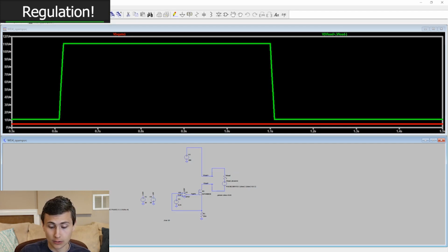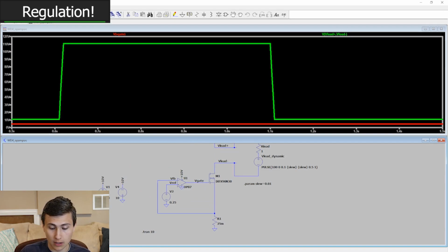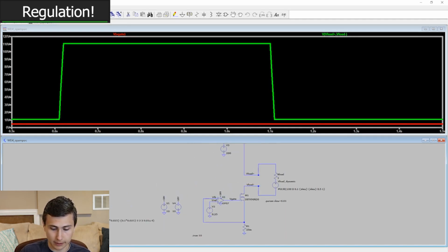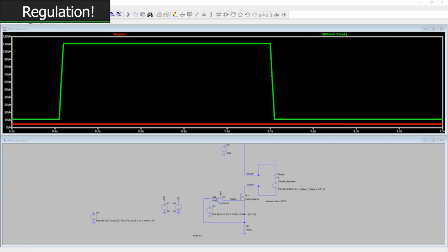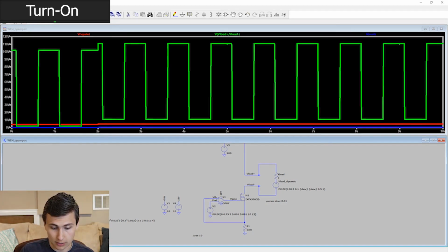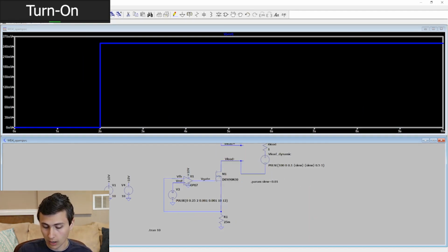Sweet. So, a couple things to note. I suppose that covers one of the things I want to make sure we talk about, the dynamic regulation. That was with a constant load. One of the first things I'd like to do to make this more aggressive is simply changing our reference from 0 amps to 10 amps, which is 250 millivolts, at a time of 2 seconds.